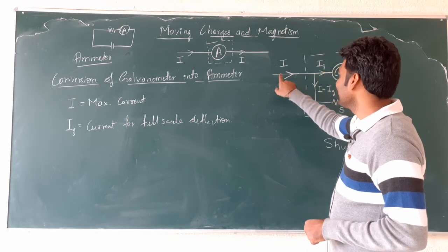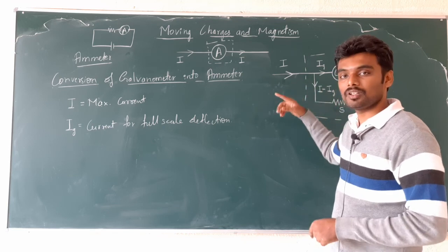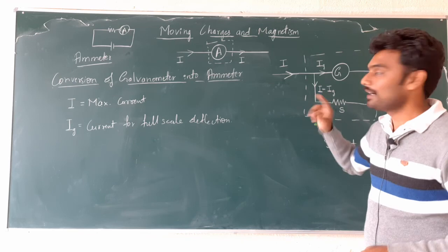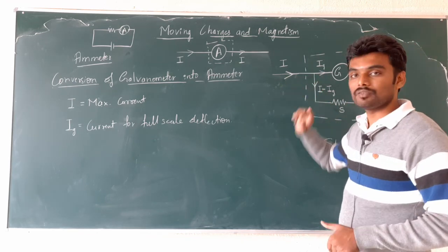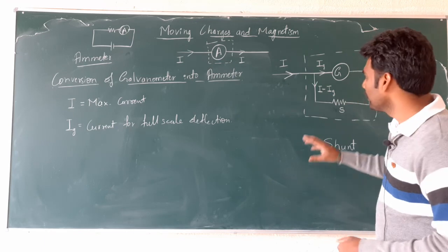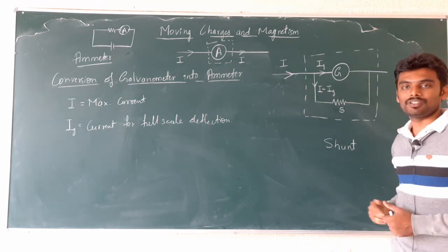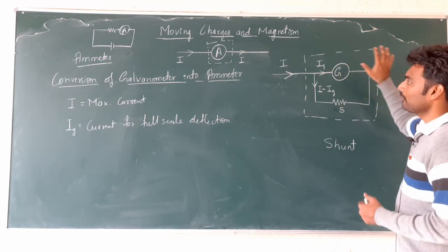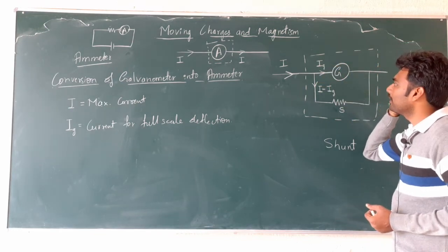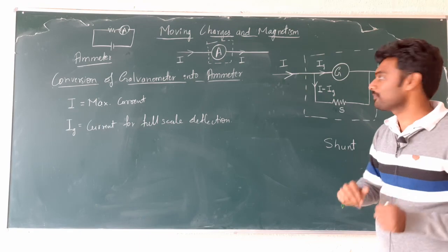Sometimes it's only in terms of 50 milliampere, 100 milliampere, 200 milliampere which flows through the circuit. And sometimes it is 1 ampere, 2 ampere. So depending on the experiment that we have chosen, we will need different ammeters here, which means that we should have ammeters of different range.